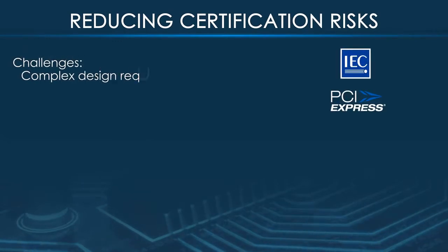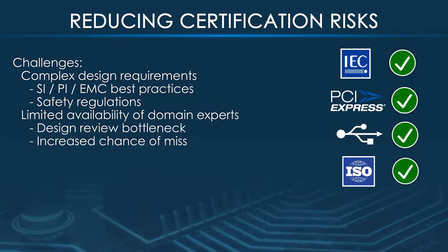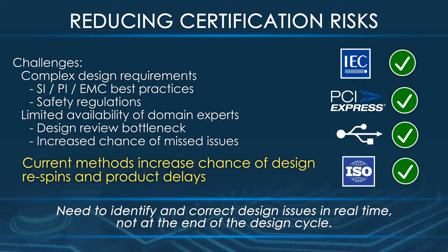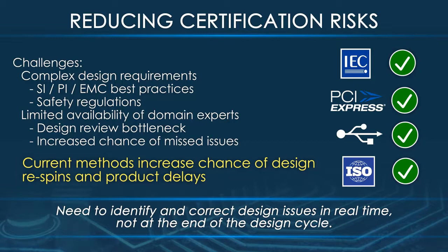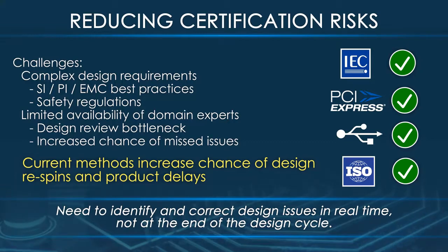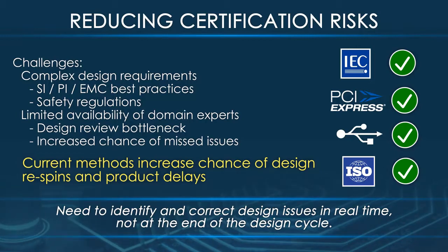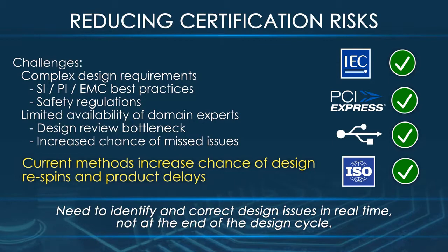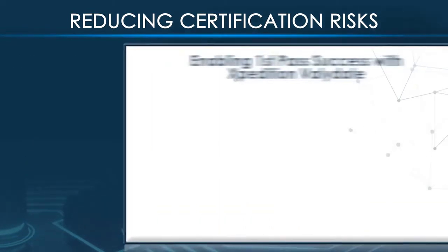Some of the challenges are complex design requirements that feature signal integrity issues or power integrity issues or EMI, EMC things, and practices on the board, as well as safety regulations such as IEC standards, the various protocols that are common technologies on boards today, like PCI Express and SerDes nets, PCIe Gen 3, Gen 4, DDR3, DDR4, DDR5 routing. All these things require domain experts, and they can cause design review bottlenecks and increased chance of respins of the board. So we need to identify these issues and correct them.